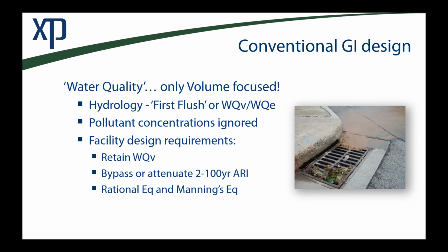So how do we deal with the runoff from a site? Well, the first thing is we size our individual facilities and ultimately our entire treatment train to retain that water quality volume event, that first inch of runoff. Our treatment train needs to fully contain and infiltrate or treat that volume. Well, that 1 inch event often isn't even the 2-year storm. It might even be less than that.